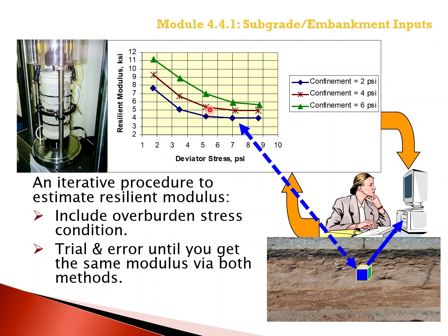That iteration is completed until there's basically a small difference between the laboratory measured value and the value selected and used in the elastic layer program for calculating stresses and strains.